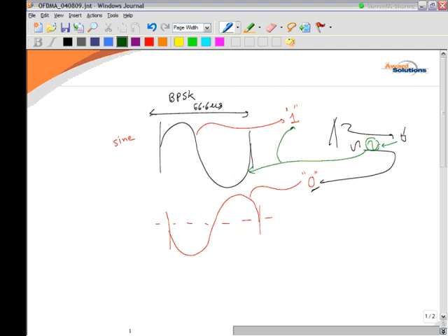It means the base station wants to send me bit 1. So basically, the modulation symbol is nothing but a representation of bits, and we do that in the form of some sine wave and cosine wave.